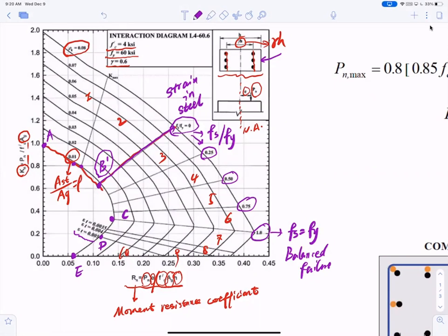There was some internet disconnection. Okay, so if I am given the cross section of the column, and given the reinforcement and told the position of bars, I can basically come into this diagram to directly obtain my interaction diagram. There's one interesting phenomenon here, okay? There's one interesting phenomenon, that is the width of the column is not given. You don't have to provide a width for the column, okay?